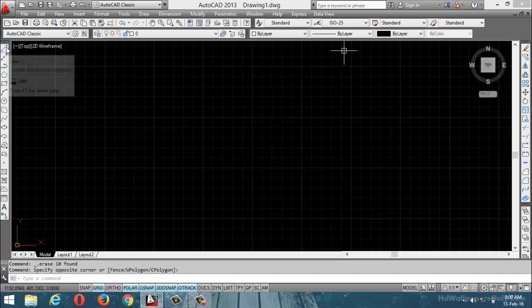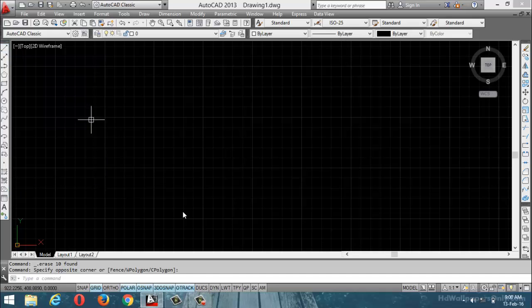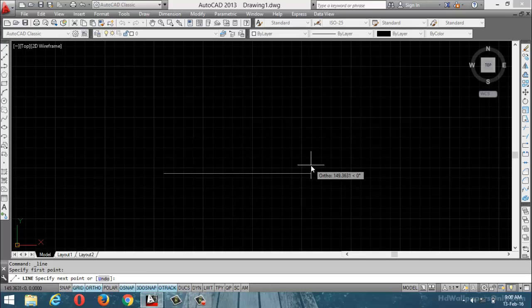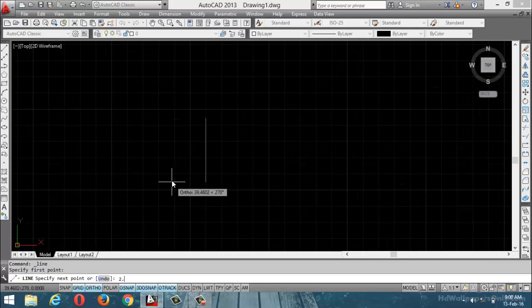Now see here, the design, what type of lines are they? All the lines are straight lines. For that purpose you can activate the ortho. Then I select the command and select any first point. First I am going to design in this direction. How much? 2.10. First I am going to design the inner one. Then again this side.